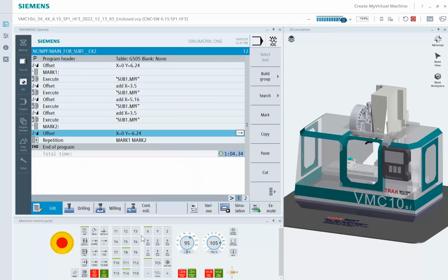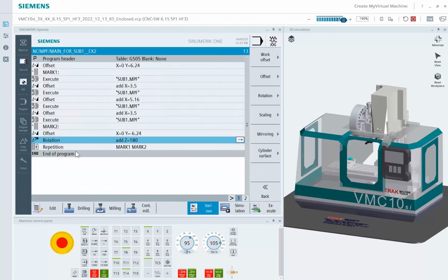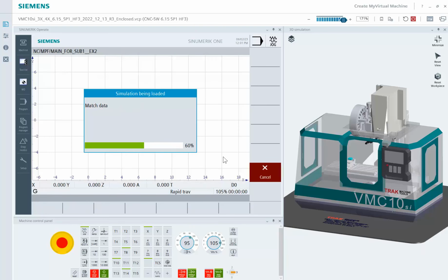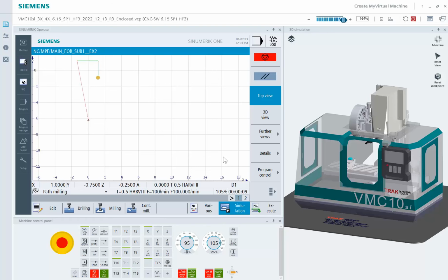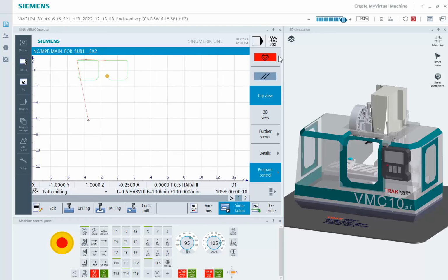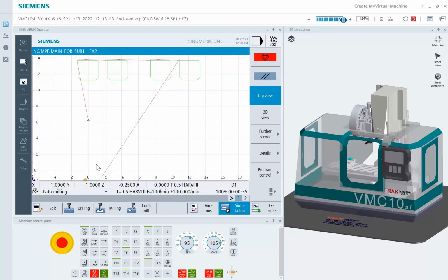Before we call up our features, I'm going to go in and, oops, I'm going to go transformation. I'm going to do a rotation. I got to do an additive because I don't want to cancel my 0 shift. And I want to spin it 180 degrees. Plus or minus doesn't matter because I'm going a full 180. So that would spin my coordinate system, and then I start to call up all my parts. But if my coordinate system's spun, that means my x plus is the other direction. So if I'm right, there's 1. 100%. Okay. And now we're going to go there.